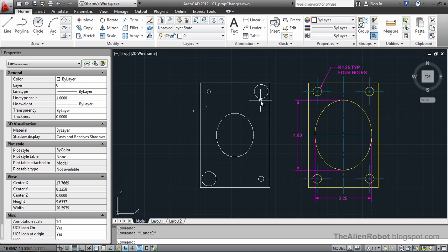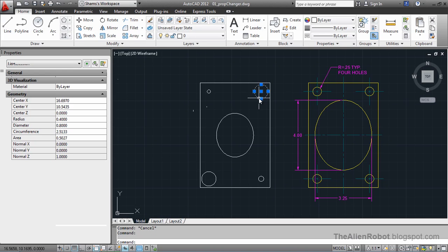Now we want to correct these value errors in these circles. It should be identical to this example I've got here. I want to change the radius of the circle here, which is supposed to be 0.25. I'm going to go to the geometry group and here to the radius, and I'm going to type 0.25 and enter. We changed that. Now I'm going to press escape.